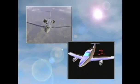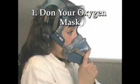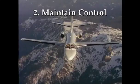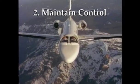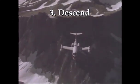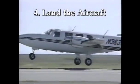If you experience a decompression, you should 1. Don your oxygen mask, 2. Maintain aircraft control, 3. Descend, 4. Land the aircraft.